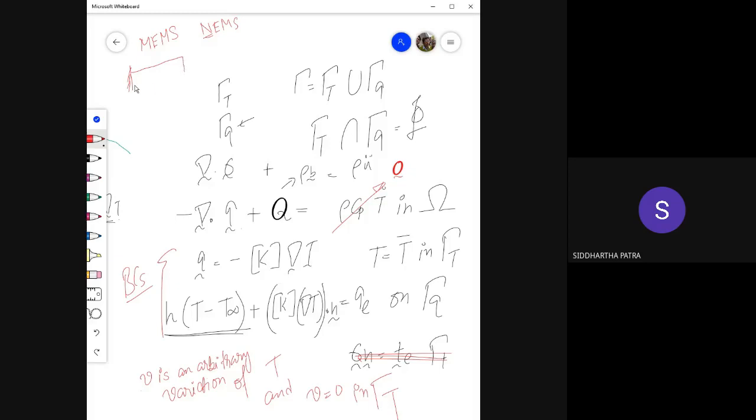So this is how the structure might look like. You can imagine there is this rectangle, and then there is this tiny portion coming out of it, which connects to another rectangle and eventually connects to the wall. What basically is done is you apply a voltage difference over here, delta V, across the two ends, so electric current flows. As you might know, whenever an electric current flows through any conductor, that eventually gives rise to heat generation. So obviously it would be changing the temperature.